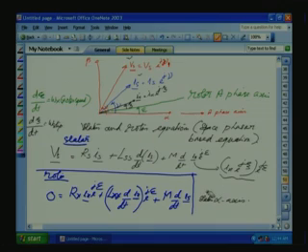Now, how much of this current, in what way it induces voltage in the rotor, we have to find the component of this current, we have to define this current with respect to the rotor axis. Then multiplied by M, that is the voltage term induced in the rotor due to the stator current.